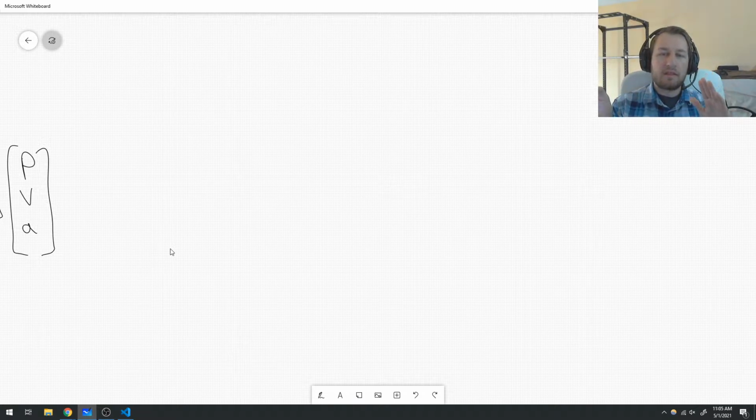The previous examples I have shown all rely on the fact that you have zeroed out the acceleration. If your rocket is sitting on the pad and it's not moving, the acceleration should show up as 0, not negative 9.81. You should take that bias out, and it should be close to 0. We're also assuming that your barometer bias is zeroed out, so your barometer is fluctuating around 0 if it's standing still.